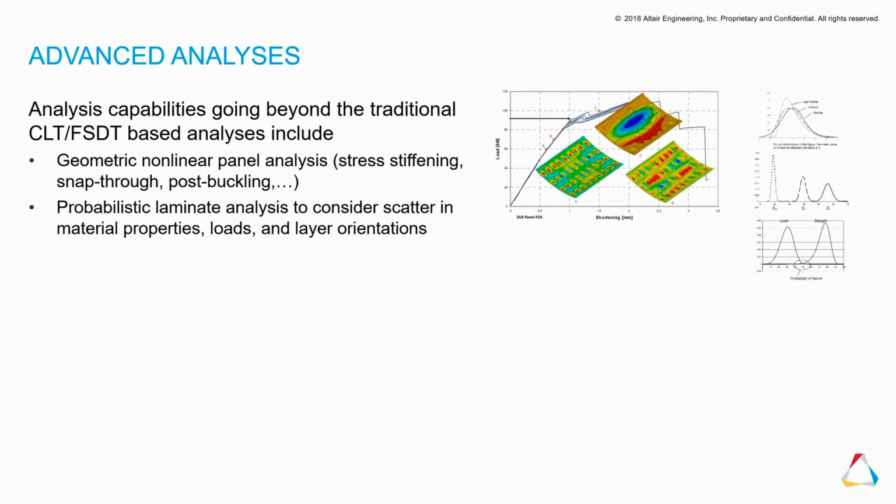Then we look at a certain end property of a laminate, let's say stiffness in a certain direction, or strength, or thermal expansion coefficient, and get the statistical distribution for that, or maybe more practically, what is the probability that the stiffness, for instance, is at least a given value. As we know, the scatter in material properties is high in composites, and this kind of study can give good insight into what properties we can actually expect for the end product.